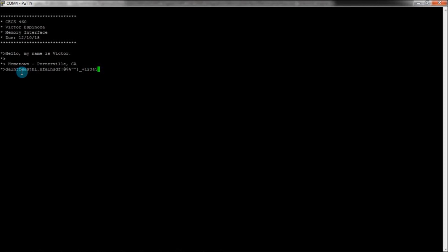Every character that I type into the terminal is also written to the Micron memory located on the Nexus 2 board, starting at memory location 0x000. Each address location corresponds to 16 bits of data. Data can be written up to memory location 0x200 in the Micron memory. Characters that are received after this limit is reached will begin to overwrite the characters previously saved in memory, starting at the beginning at memory address 0x000.